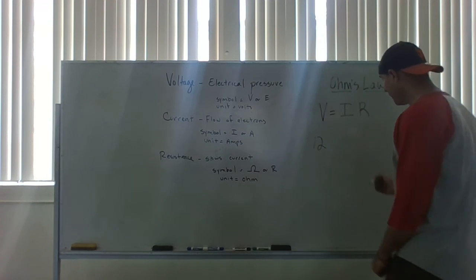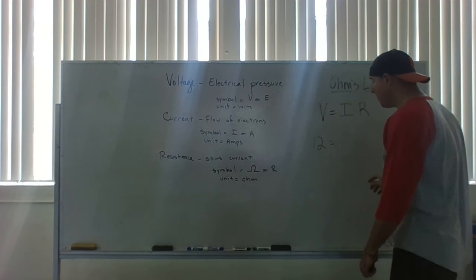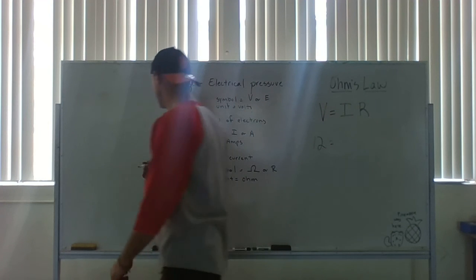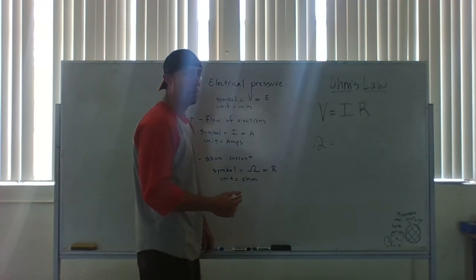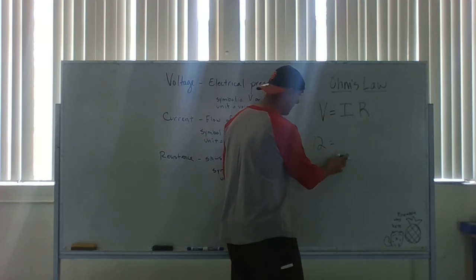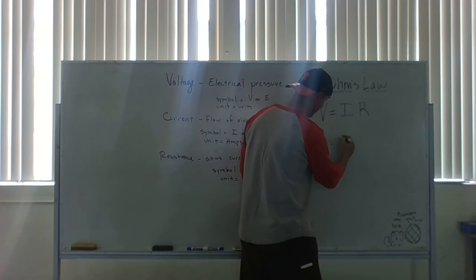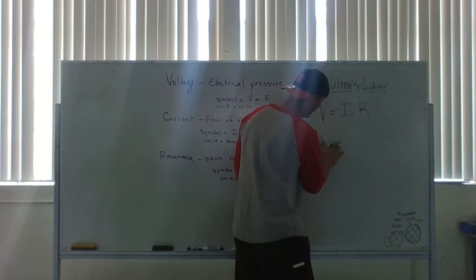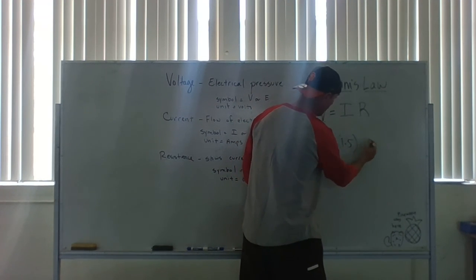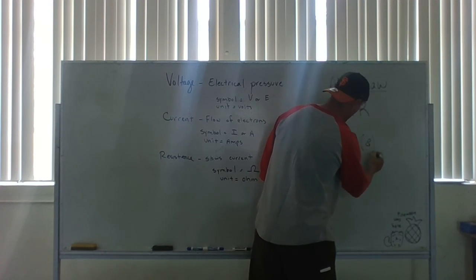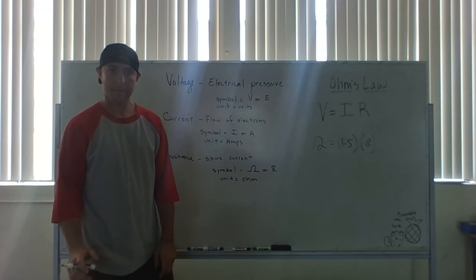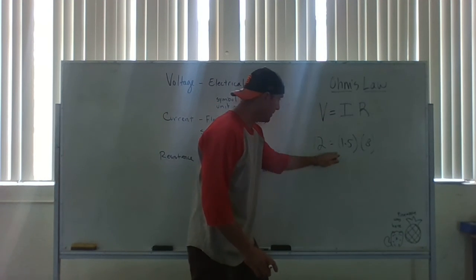So, let's say I'll go back and look at that light bulb. I'll take a look at that light bulb and it'll say, hey, that light bulb is rated for 1.5 amps. All right? So I have 1.5 amps. And so based on this equation, I have 8 ohms of resistance in that light bulb. All right? That balances this equation.